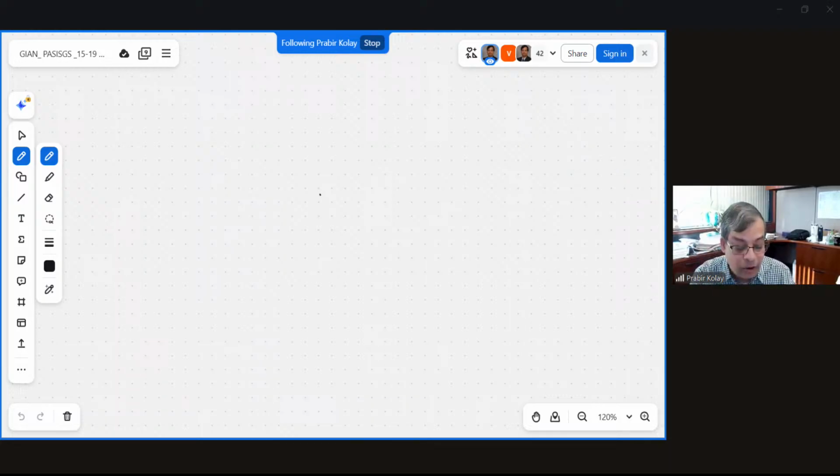Problem 10 is the vacuum preloading with PVD used to improve a 20 meter thick soft clay layer. Basically, the equivalent vertical permeability of the PVD improved soil is given as 3 times before improvement. Determine the optimum penetration depth of PVD for the vacuum preloading. So you need to calculate that for the PVD vacuum preloading.